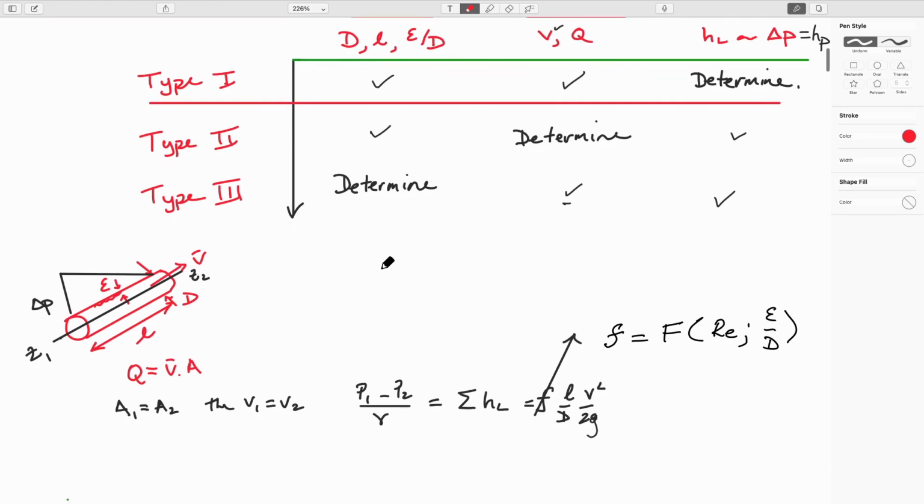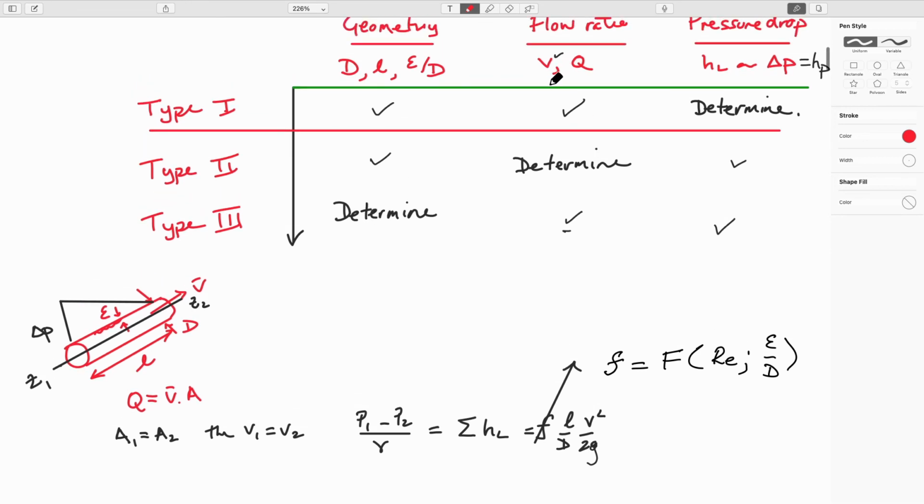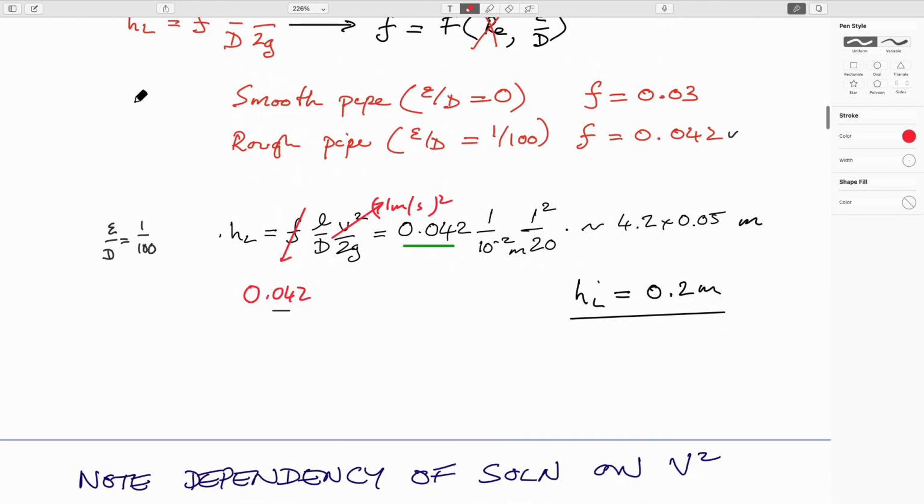And the more difficult one is where you want to dimension the whole system based on the velocity term. Defining the volume flow rate you want to get out of your faucet in the morning, the pressure you get out of the mains going into your house or by your tank if you live on your own well, allows you to determine exactly what the pipe diameter should be. And of course, having a much bigger pipe diameter means that you can always get that flow with whatever head loss you have, but that means you pay more for your piping in the house. So that's an optimization. So that's it for today.